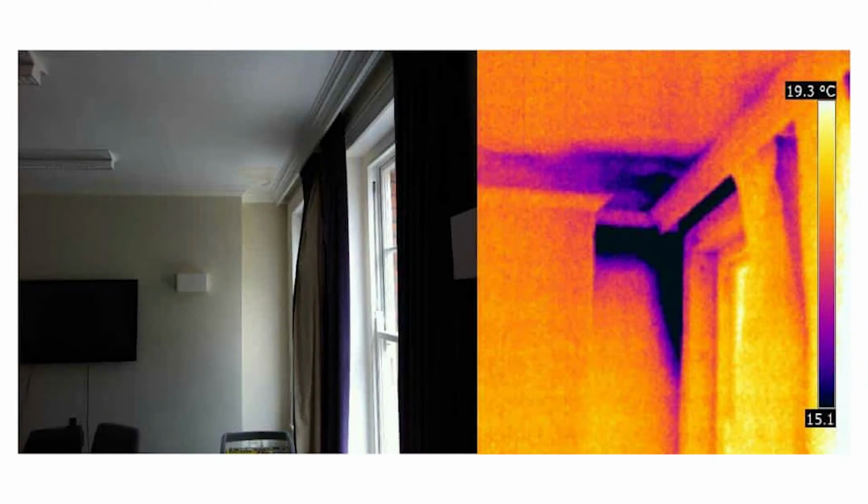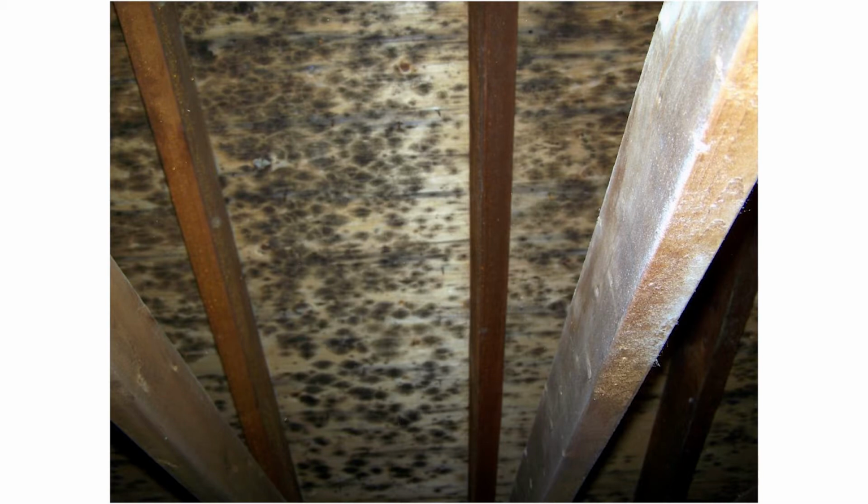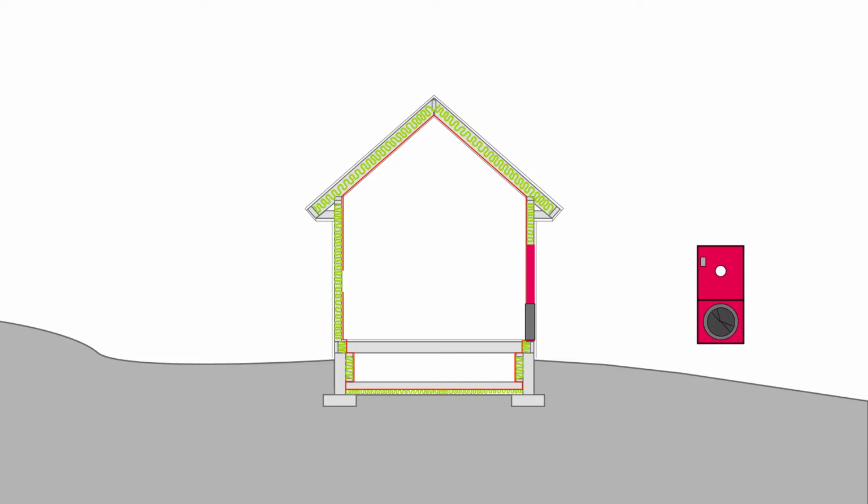energy consumption. Uncontrolled air leakage also carries moisture which can flow through the wall and roof assemblies, condensing as the temperature drops below freezing and often gets trapped in the enclosure system. This can cause mold and rot in serious conditions.